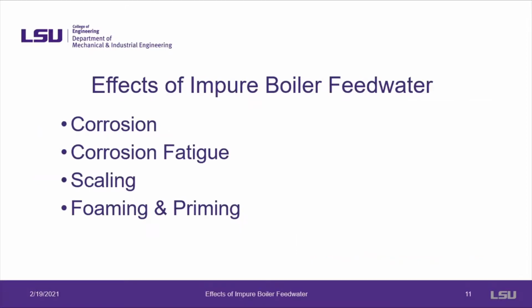Impure boiler feedwater can cause four main issues, which include corrosion, corrosion fatigue, scaling, and foaming and priming.